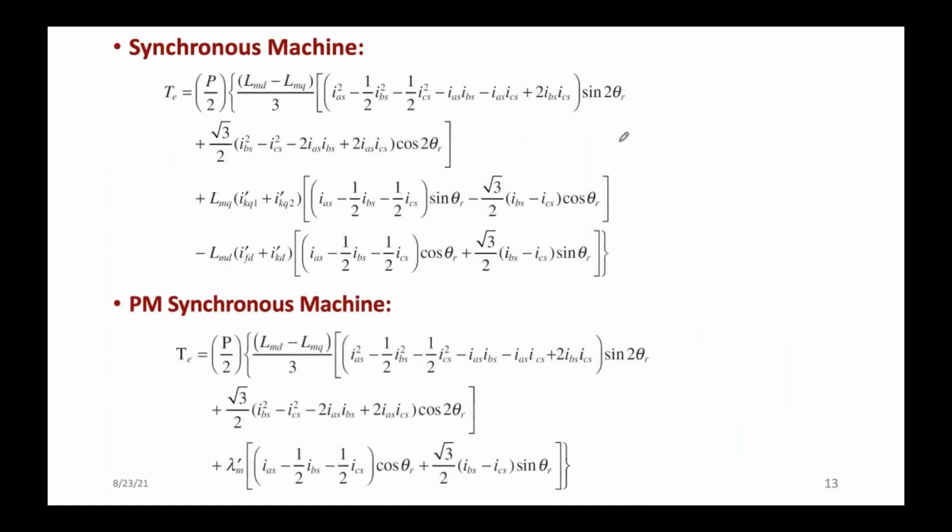So now I will try to explain the induction machine by taking the universal torque expression, and why torque control is very complex in AC drives. With Zs, Zr, sin delta in the case of the induction machine, we can decide how many state variables are involved in the torque expression. That is the first step.